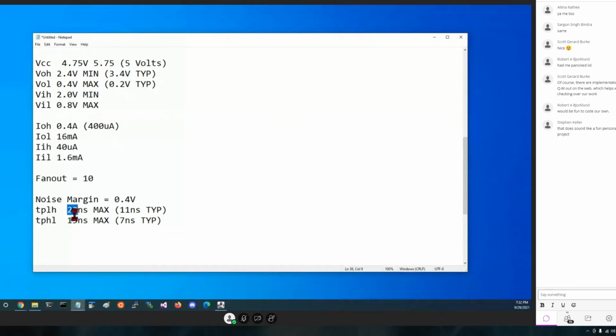And since these are different values, you may get some intermediate answers as you're changing some bits on and some bits off, telling us that although combinational logic on paper happens instantly, in the real world, we may have to put some delays as to when we look at signals in order to properly know they've changed and they're stable. So this would be some numbers I'd want to have somewhere.